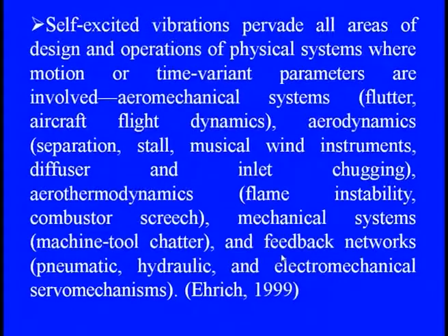Even in the aerodynamic part, there are fluid or flame instability and combustion screech, and in mechanical systems, as we discussed, machine tool chatter, even feedback networks where the damping is applied, and pneumatic, hydraulic or any electromechanical servo mechanism. These are all varieties of applications where self-excited vibrations come due to their inherent nature, and this was analyzed by Ehrich in his own paper in a very significant way.